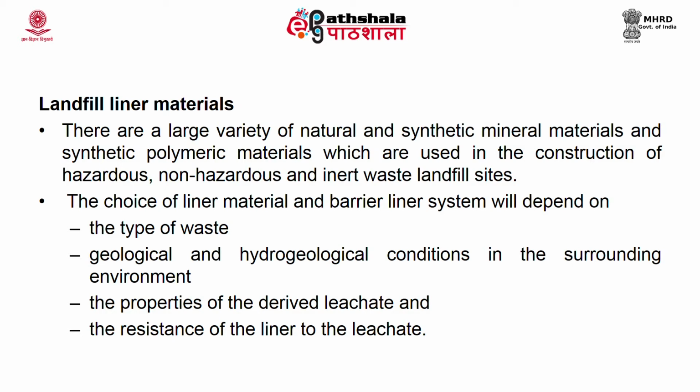Then you also have to look into the resistance of the liner material. How resistant are they to the chemicals? Because landfills mean numerous chemical substances are released into the leachate or present in the waste, which can again puncture or create holes, leading to leakage, and then the liner system will not be efficient enough. So, the resistance of the liner to leachate and to other chemical substances should also be taken into consideration before you choose a liner material.